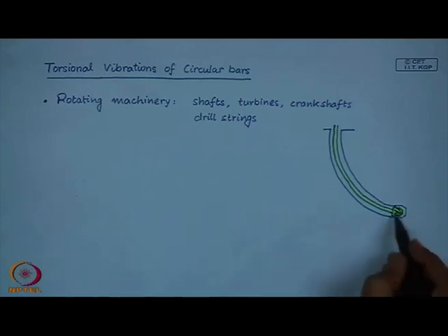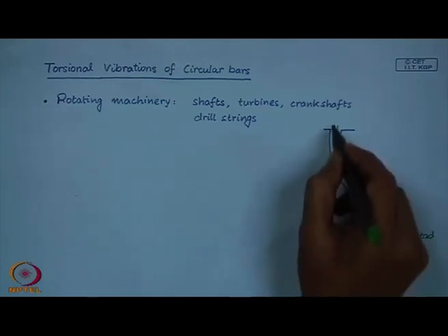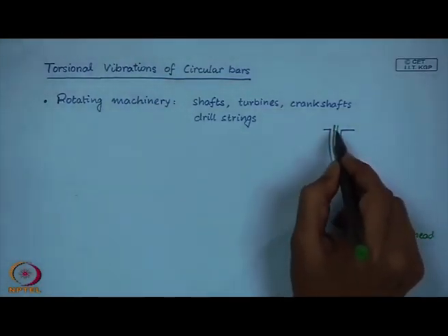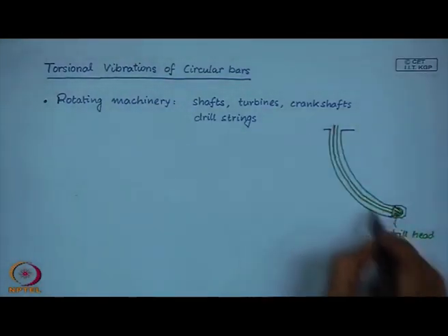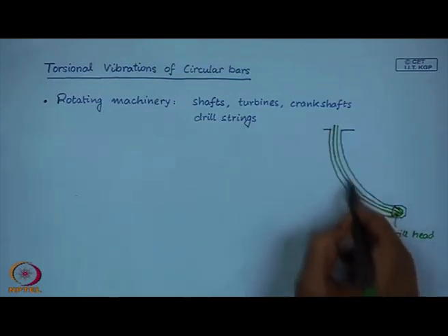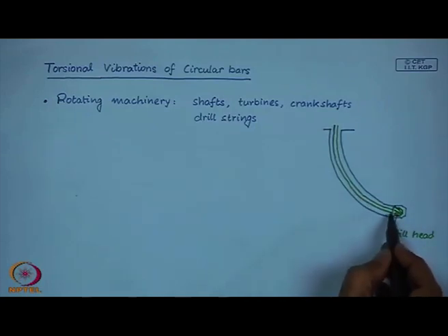so this is the drilling head, and here you have a shaft which transmits the torque to this drill head. This shaft is under torsional vibrations.